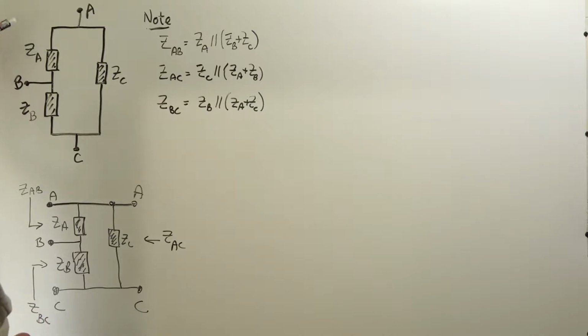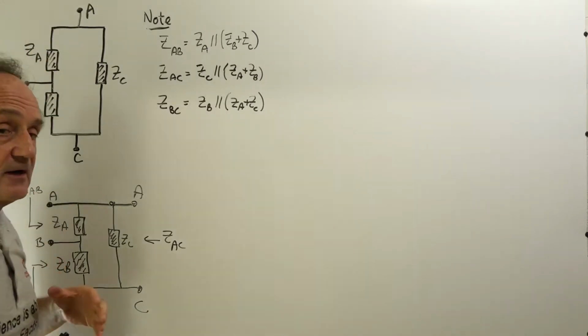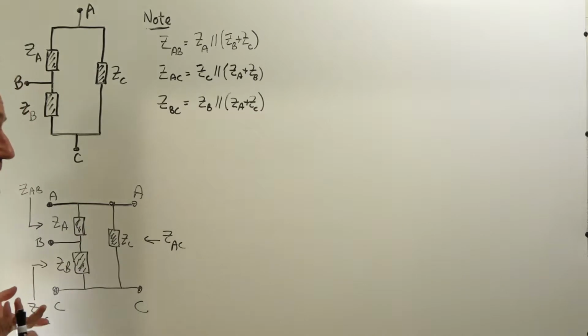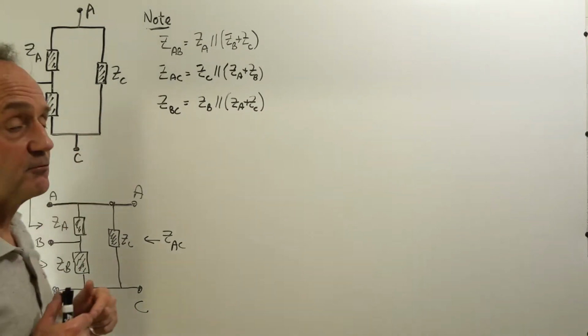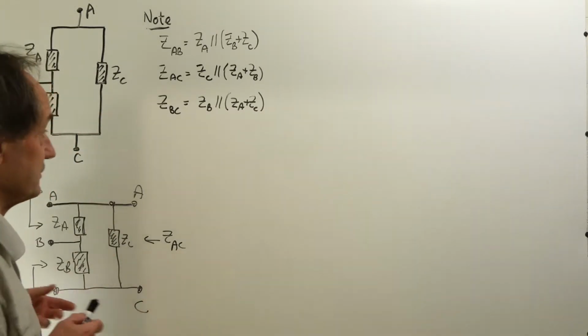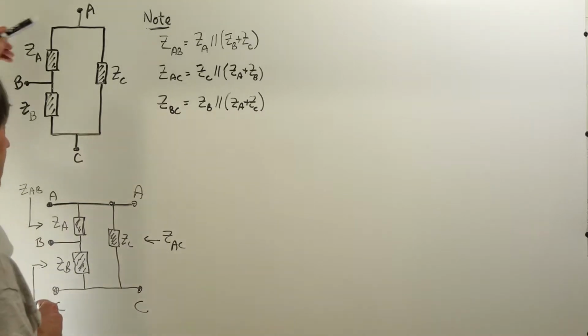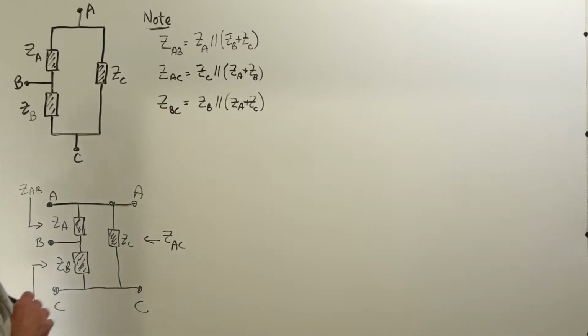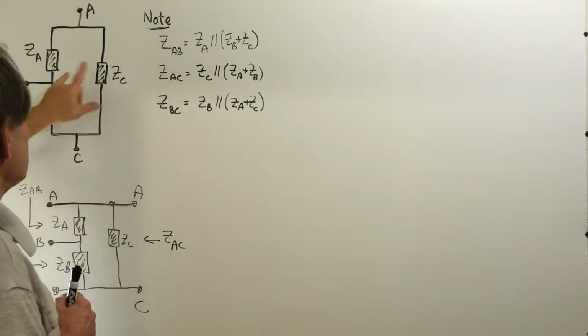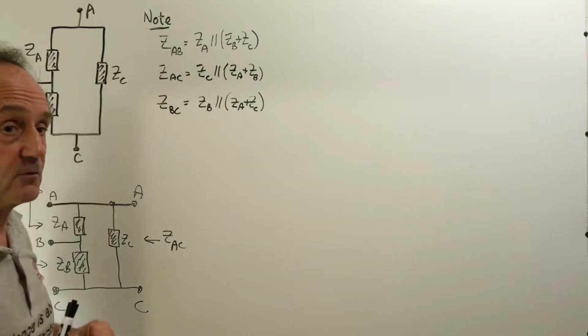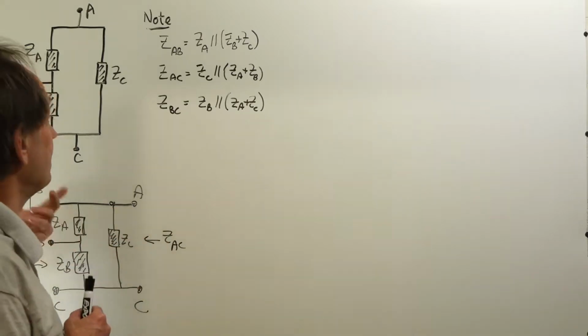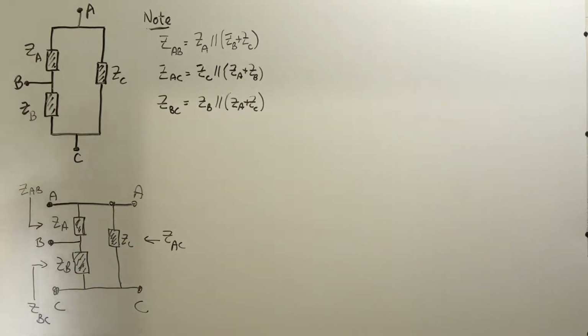So I'm going to solve this circuit in general using generalized impedances. The Z's could represent resistor values, but this is just very general. These generalized impedances, which in AC circuit analysis would be complex numbers of magnitude and a phase angle, but in a resistor network these would all just be scalars.